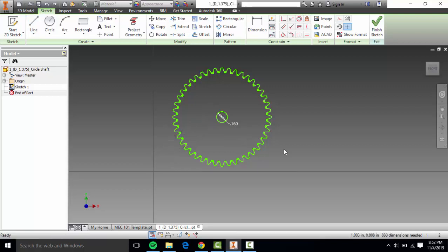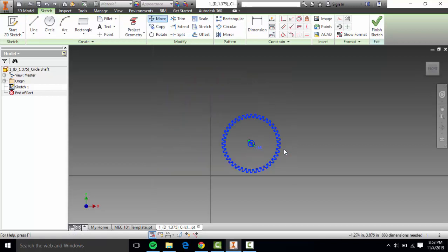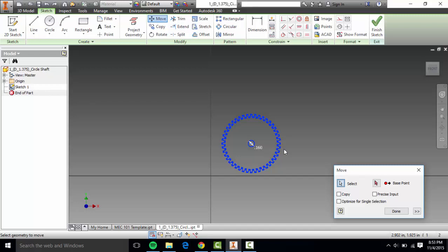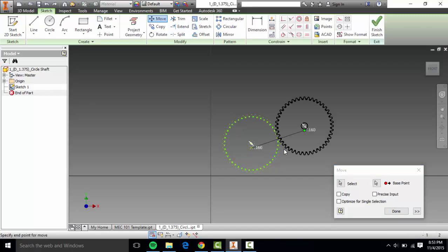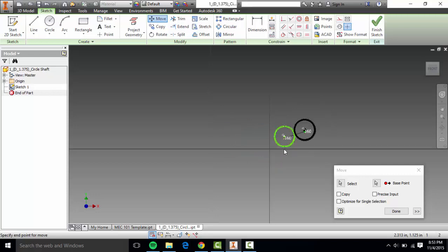So what that means is Inventor copies and pastes with the origin as a base point. So if you wanted to copy and paste it into a different location into your new file, select the Move button in the Parts Database file, move it to a different point, maybe like all the way up here.